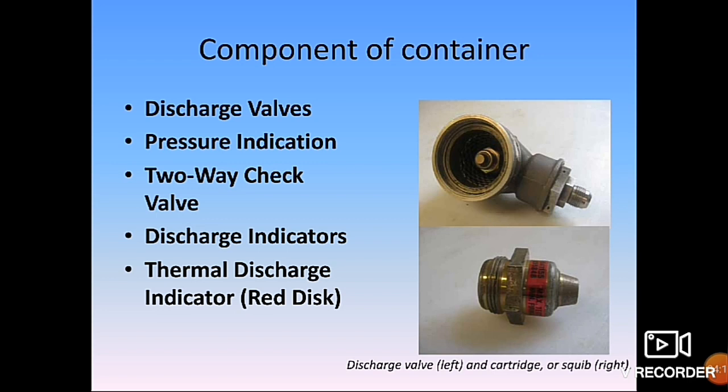The second one is pressure indication. A wide range of diagnostics is utilized to verify the fire extinguisher agent charge status. A simple visual indication gauge is available, typically a helical Bourdon type indicator that is vibration resistant.